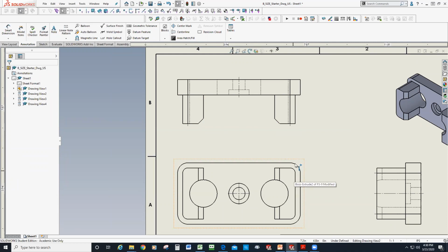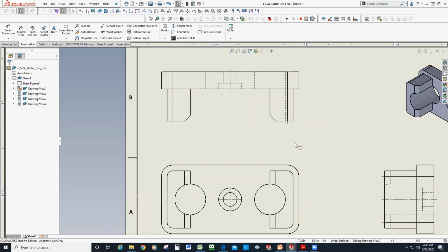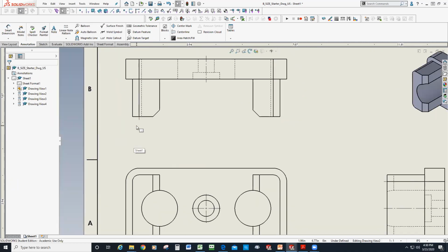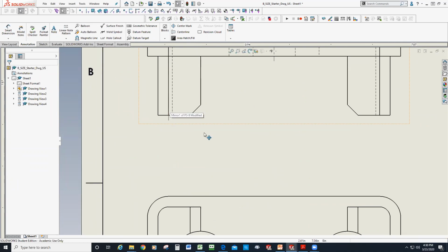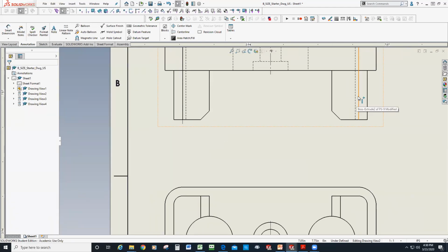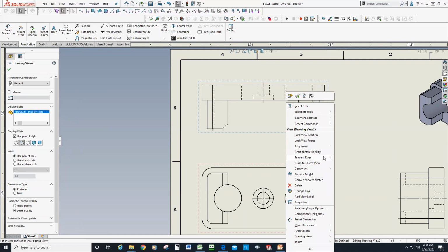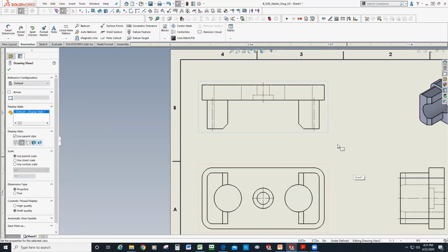And then it also looks like it puts center lines in this view that correspond with these radiuses. And once again, they're kind of in the way. But you can see at least that the center line does not override the visible line, even though that visible line is a tangent line. So one of the other options I guess I could do is, if I undo this, so that center line is back there, I could go to this view and highlight it and say I want to remove the tangent edges. And now you can see that center line there. So you took away those tangent edges.